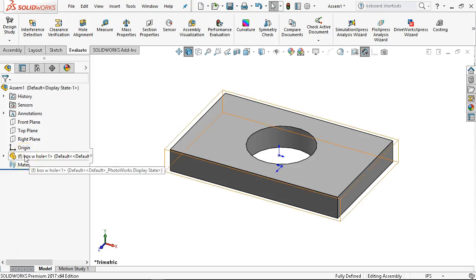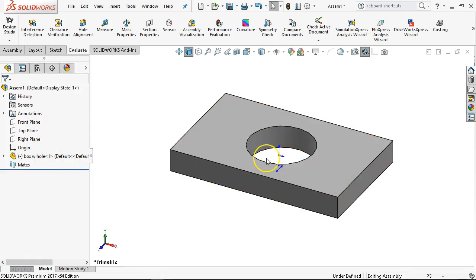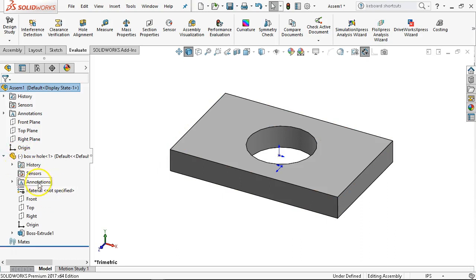It's the first part, and so we're going to float this because I do want it in relation to the origin. Unless I'm going to create that coordinate system, any mass properties, mainly the center of mass calculation, is going to come off of this origin, when maybe this is really the base that I need or would want. All right, so we want to make sure that we have that first selection.